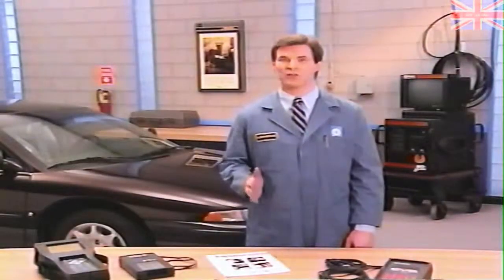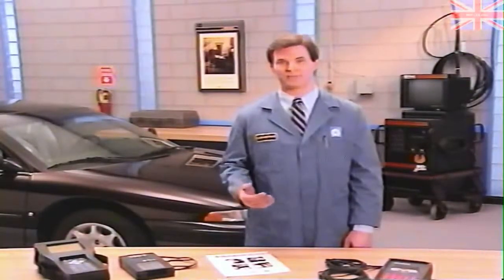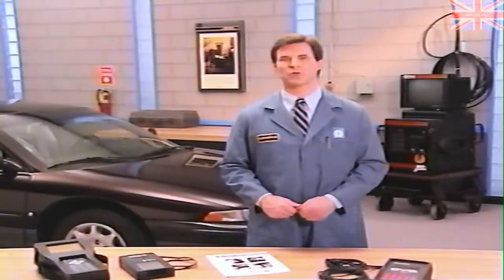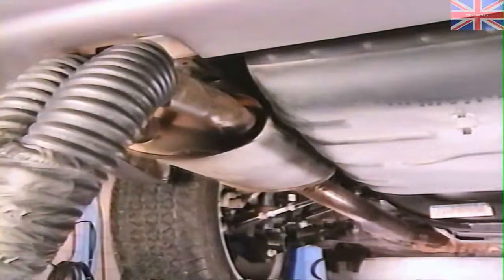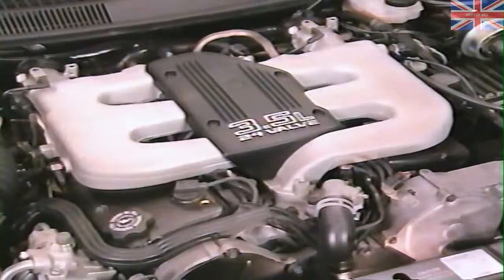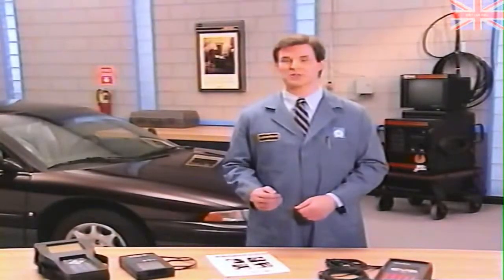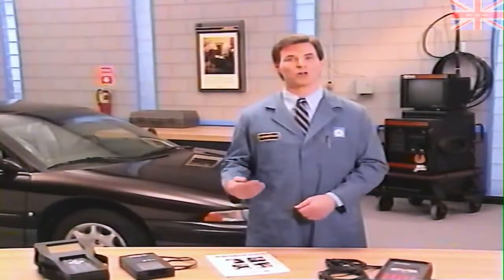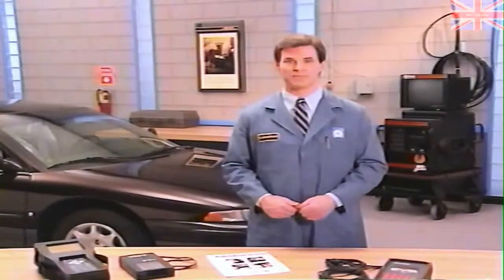If beats occur only when idling, your possible causes are somewhat more limited than beats that occur when driving. A beat while idling can result from one or all of the following: differences in frequency between the engine and the accessories, between the engine and exhaust, between the accessories and the exhaust, and even between the engine and the engine's own firing impulses. The problem is compounded when driving because any one of the frequencies we just mentioned can combine with one or more vehicle speed-related frequencies, like wheel speed or half-shaft speed.